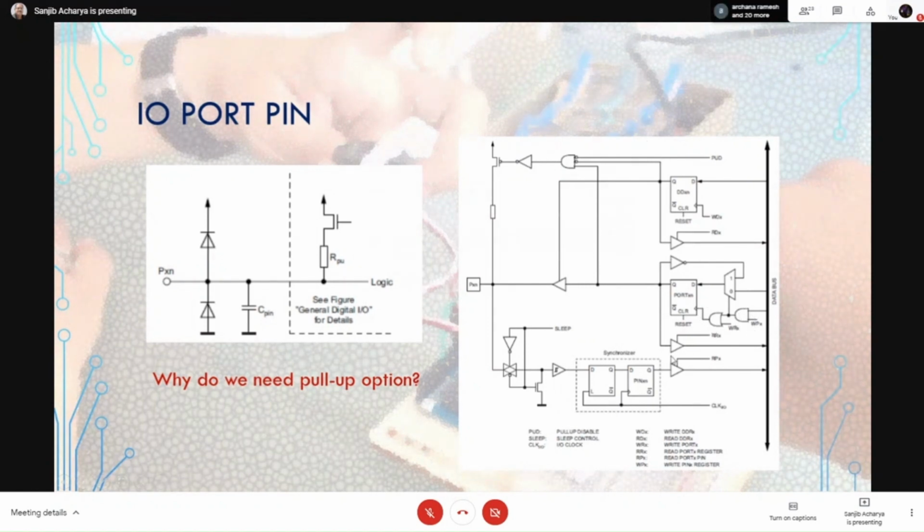All these gates and logic will be used for configuring this as input or output. And there is an option to have a programmable pull-up resistor for each pin, shown here also. Either you can keep the pull-up, or you can turn it off.